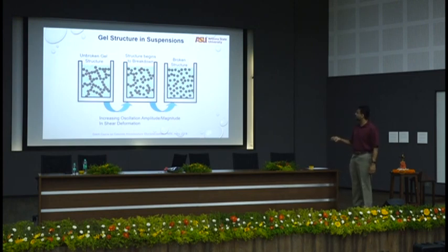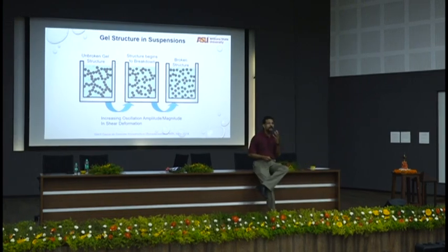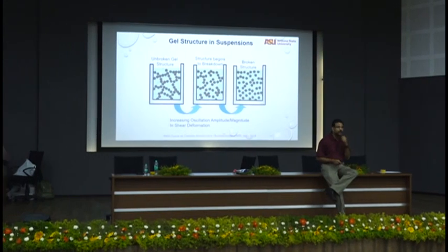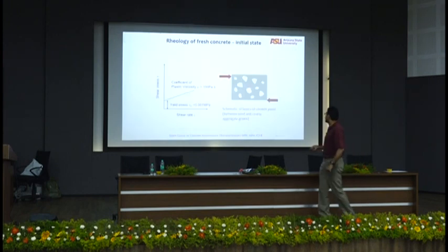When you have an initial structure, they're all bound together, and by both mixing as well as admixture action, you break the structure down, because you're not going to get these particles, for example, hydrate well in this state, but if you are like this, you will get good hydration. So rheology is also important for hydration. Good rheology of the paste is also important for hydration, because if the rheology is not good, you won't have water that's dispersed all through for good hydration. So microstructure formation is dependent on rheology. Okay? How does a microstructure form is a question of what is the rheology of your system.